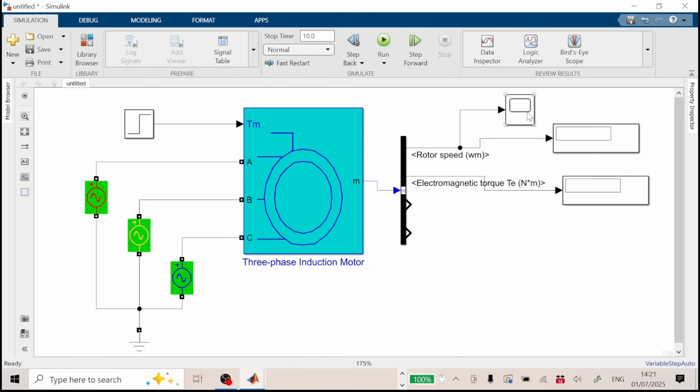Fine. So you can measure the current as well, you can measure the rotor current as well. For the stator current, if I measure that one, it's going to give me an instantaneous value. So it's not wise to have a display, but I can put a graph or put a scope. But also I need to measure the amplitude and angle or RMS value and angle.